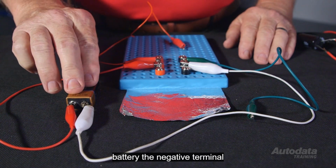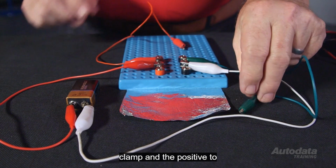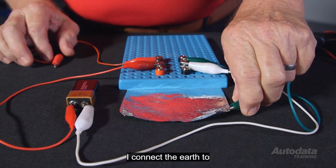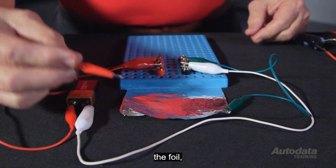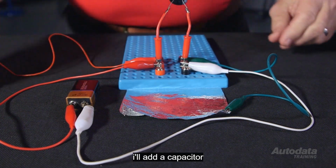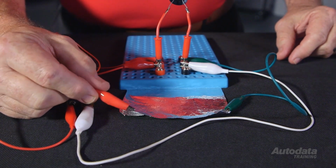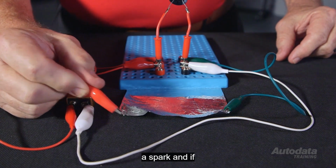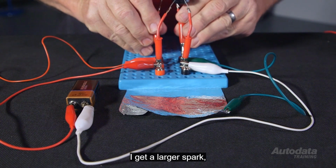Capacitors have the ability to release their stored energy very quickly. Here's a 9-volt battery. The negative terminal is connected to an earth clamp, and the positive to a probe. If I connect the earth to a piece of foil, and then touch the probe to the foil, nothing appears to happen. I'll add a capacitor and see what happens. This time we get a spark. And if I add another capacitor, I get a larger spark.